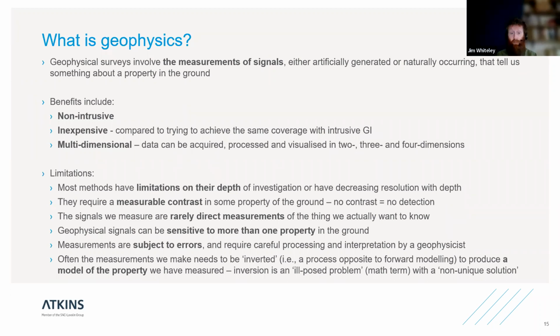And as I've also said there, the sensitivity of these measurements are not exclusive. So, for example, we could have very wet, very clay-rich ground, and it would be very difficult to differentiate between which of those is actually causing the change in, say, a resistivity signature.